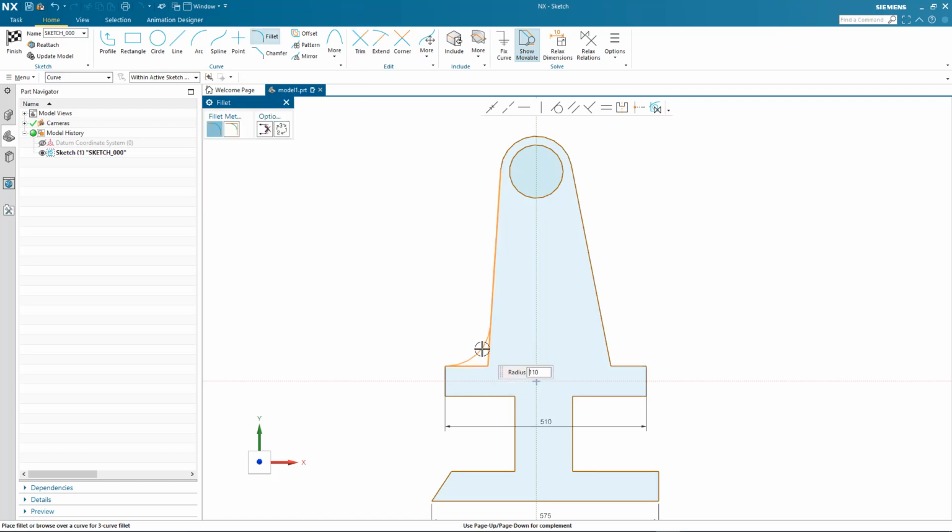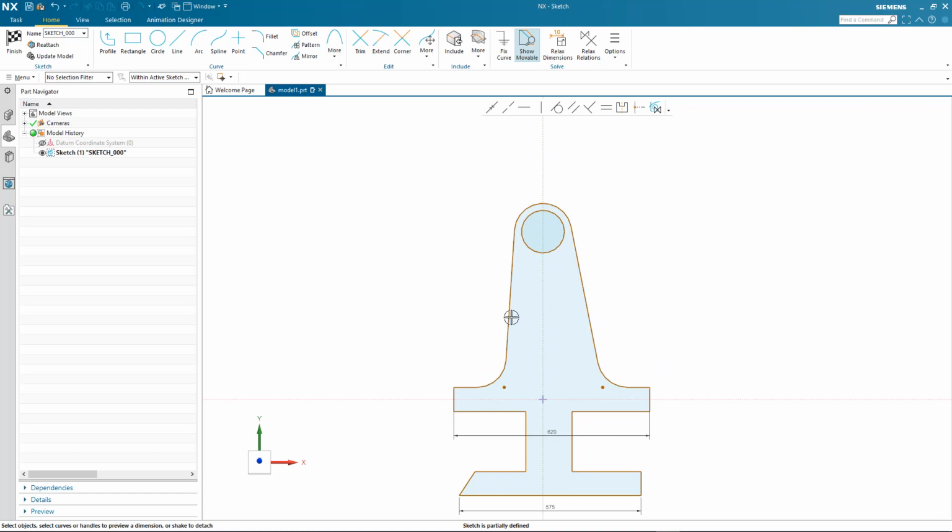We'll add a couple of fillets. And again, we'll just make a modification. Change the dimension, either end again. I'll continue to define our profile by adding a further dimension to control the height of that diameter. And again, you'll notice the relations found, and also as I drag the dimension up and down, the point on curve relation is maintained on the y-axis.